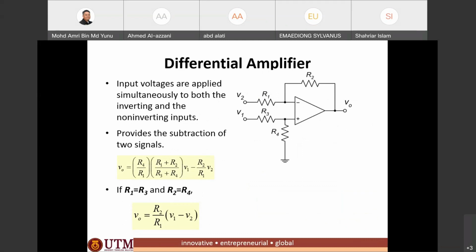Again, this is an example: good signal conditioning for a thermocouple. Remember, a thermocouple is two dissimilar wires connected together to make two junctions. It has an output with open terminal, and the output is basically the EMF.